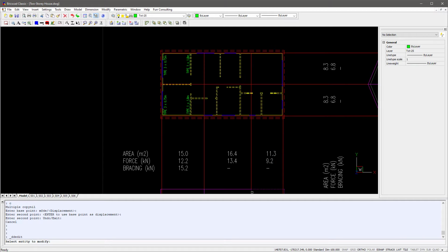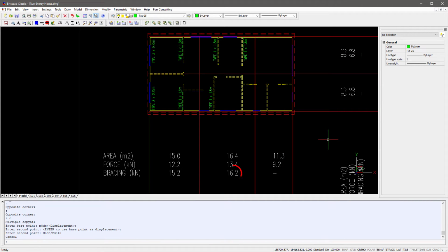Moving on to our next section, we have several long walls to pick from. We could just put 4 lots of type 1 bracing sections in here, but this might be a bit excessive. Thinking ahead, we can see there's another internal wall to the next section at the southern face. So what we can do to keep things spread out is to just use 3 lots of type 1 bracing, with 2 at the north and 1 at the south. This gives us a capacity of 16.2.